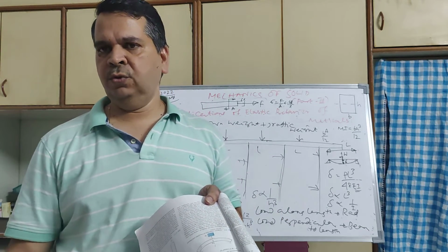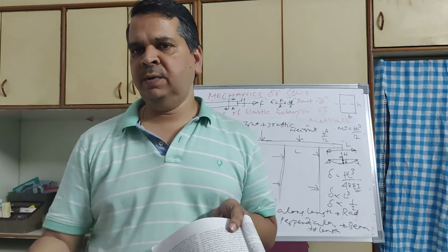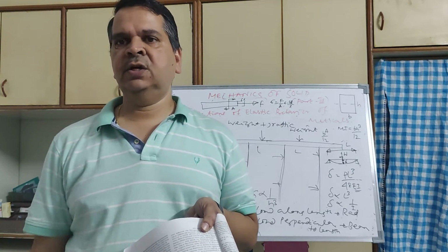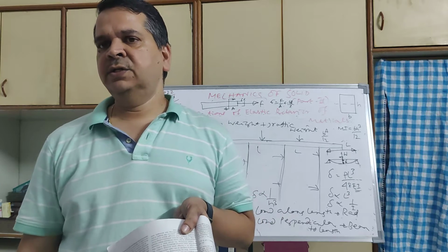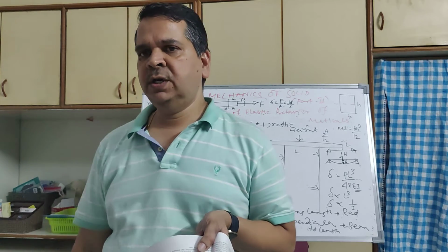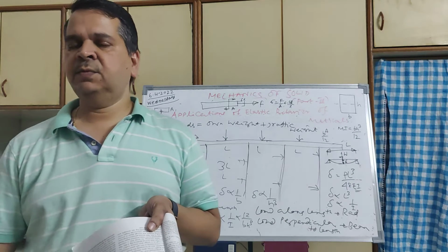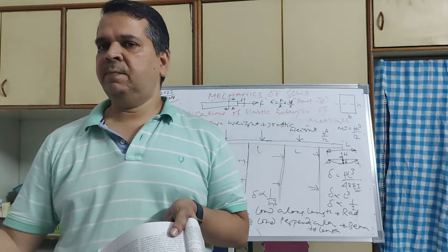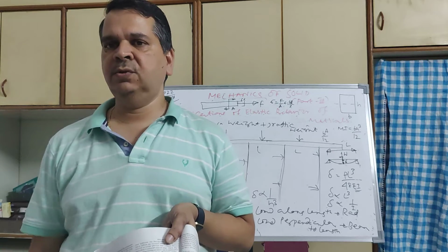by doing the force by area of the rope. Area of the rope is nothing but pi by 4 d square. So you have compared the strength of the steel, since the rope is made of steel. Then you find out the diameter, because the strength of steel is equal to applied stress. Applied stress should not be more than strength, so maximum it can be equal to the strength.